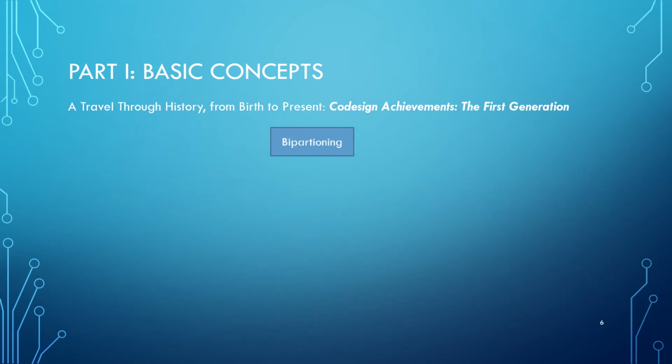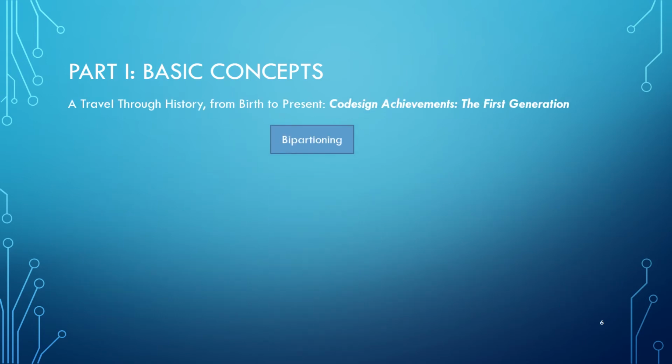In the early years, much focus had been put on tackling the problem of partitioning a given functional specification into hardware and software, hence a problem of bipartitioning. Here, two initial, quite complementary approaches are worth highlighting. In the Vulcan approach developed by Gupta at Stanford, California, the idea was to start with a hardware-only solution and to migrate as many tasks as possible to software while satisfying performance constraints, with the goal to reduce design costs.